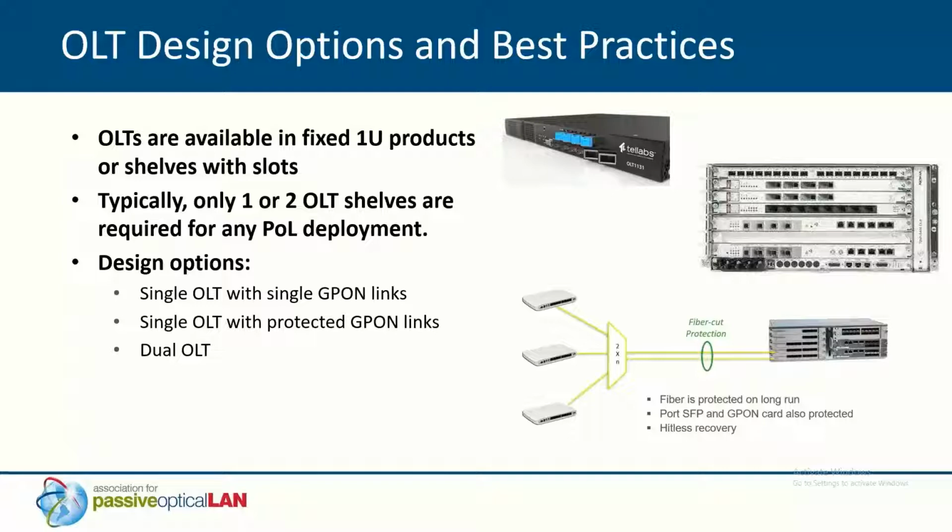The one thing that I'll add here that we haven't included is that most of these OLTs also allow for subtending. So keep that in mind. A lot of projects, I don't think, remember that that's available. In other words, I can have a master chassis that is feeding a secondary chassis, maybe in another building or another part of the property, that provides data connectivity to that secondary chassis. And it can be a 1 gig link or a 10 gig link or larger than that if required. So again, I'm going to try and focus on the flexibility inherent to a PON network.